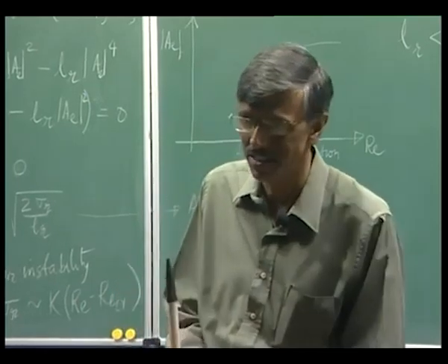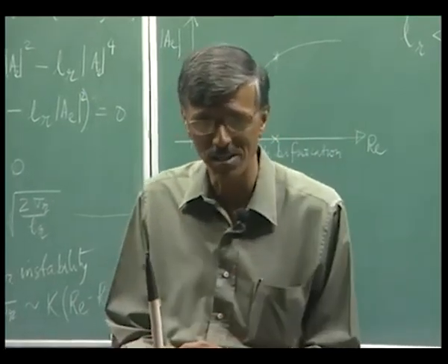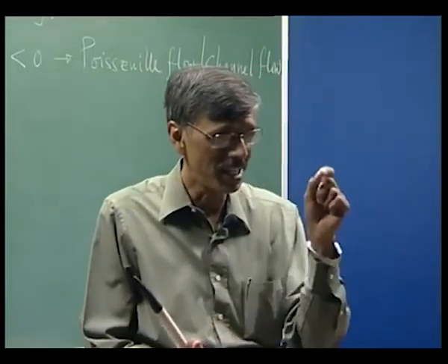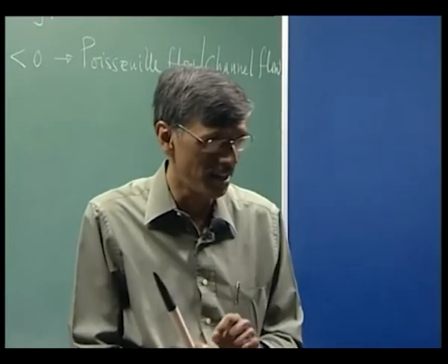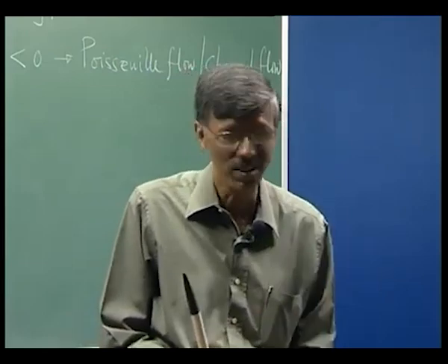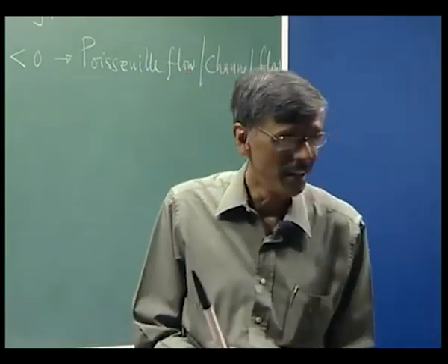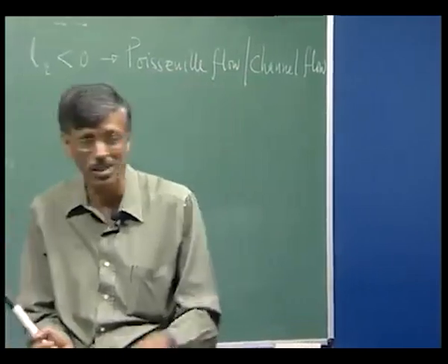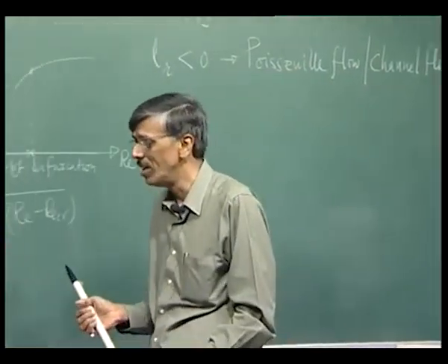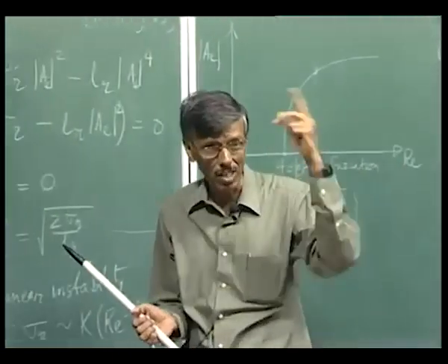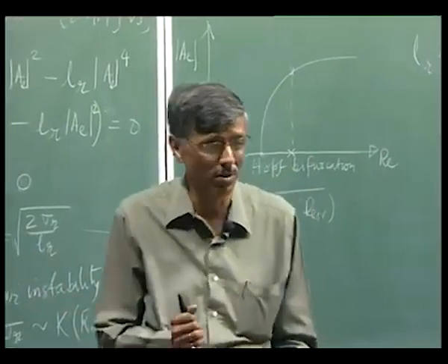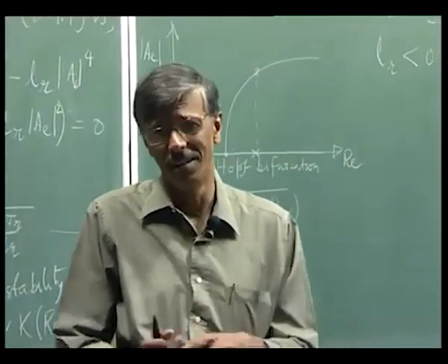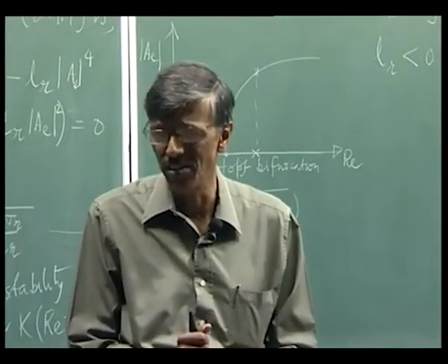We talked about the subsequent work done by Strykowski and Sreenivasan, which investigated putting in a smaller cylinder in the wake of a large cylinder and controlling the vortex shedding completely for a Reynolds number less than 120. It was shown experimentally in the late 80s. However, that started with the original observation by Kovasznay. When he put in a probe in the wake of a cylinder, the wake pattern changes.